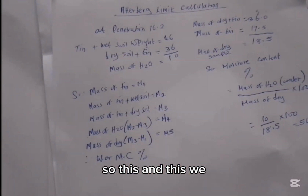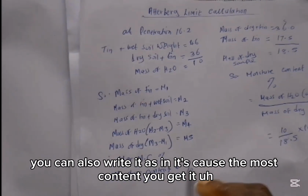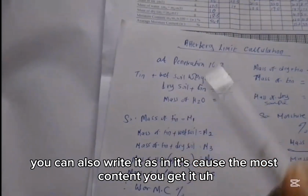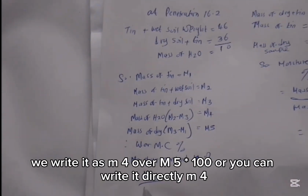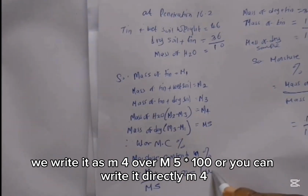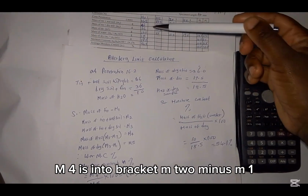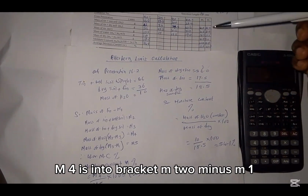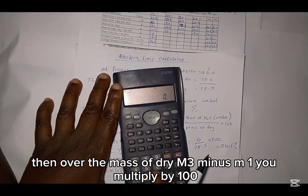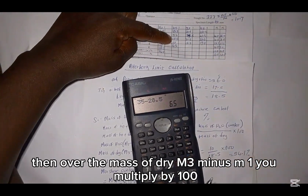So the moisture content, we write it as M4 over M5 times 100, or you can write it directly as M4, which is in brackets M2 minus M1, then over the mass of dry, M3 minus M1, you multiply by 100.